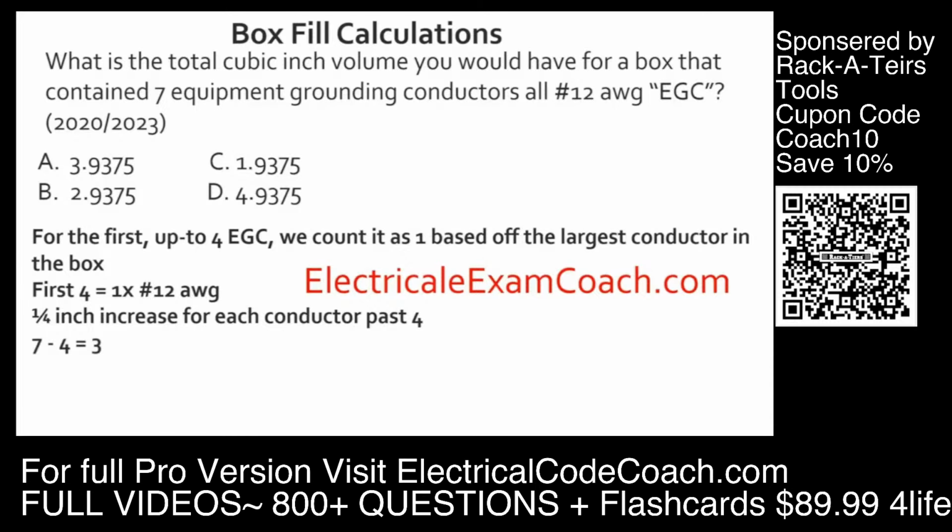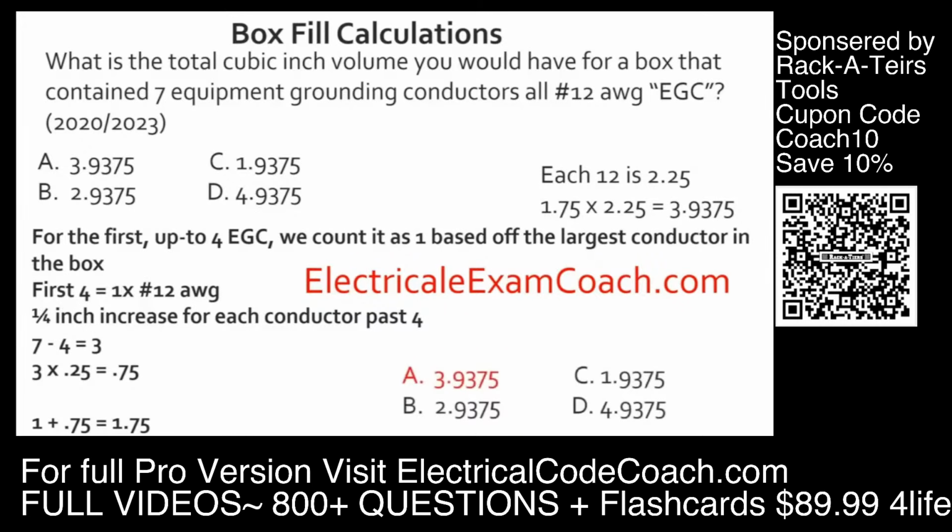We have 7 total, and we're going to minus 4 because those first 4 we counted as 1. So we have 3 left over, and we're going to take those 3 and multiply it by a 1/4. And that gives us 0.75. So we have a total of 1.75 conductors based off whatever the largest conductor is in the box. In this case, there's only number 12s. So we would take that 1.75, multiply it by the cubic inch volume for a number 12 conductor, and we end up with 3.9375 cubic inches for our equipment grounds.